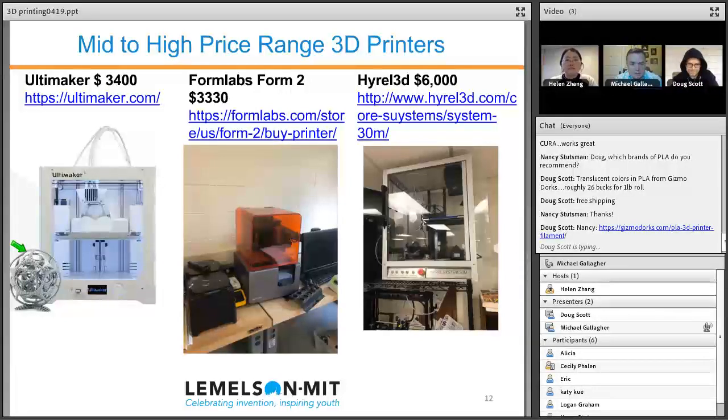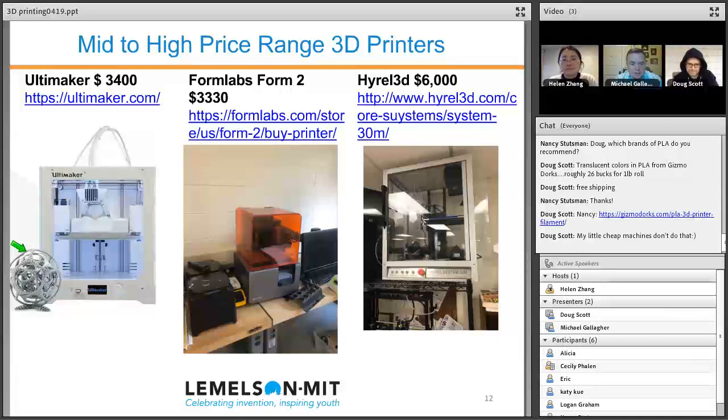If you were to make that with a traditional fused deposition modeler, which is the ones that we've been talking about so far, it would be really difficult to go in and break away all those supports on the inside. So they picked that part for a reason, because it lends itself to a dual head and something that you can dissolve those supports.